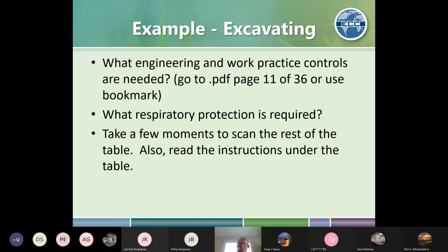Mike, this is Pete. Could you mention what we were talking about earlier about ambient dust and grounds people? Dust control. About the housekeeping and settled dust? Well, about whether you need to sample or... Yeah, if you can keep it to non-visible emissions with water. That's what we just talked about with the excavating activities. If you use water to keep the visible emissions down, then you don't need to do anything else. Okay.